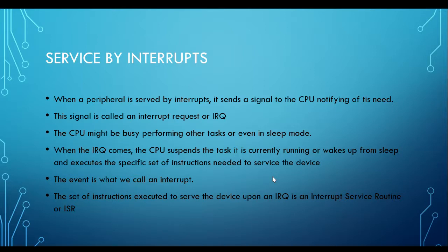Now, in this case, you don't need to check the bit every computation cycle, every main loop. In the polling concept, the main program actually checks the flag. Not so with interrupt. Okay, with interrupt, you use an IRQ to replace the manual checking. The set of instructions executed to serve the device upon an IRQ is called an interrupt service routine. So what happens when the interrupt is being called?